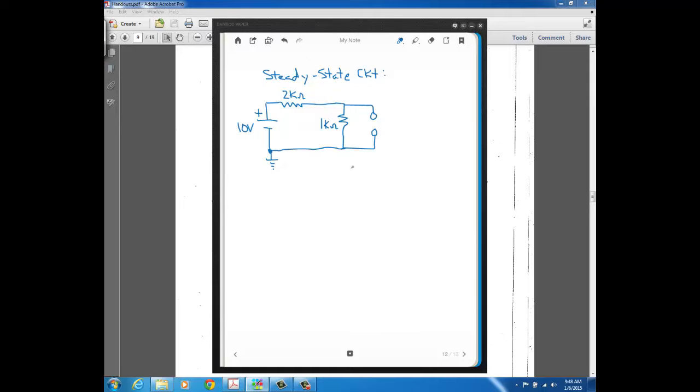the current for the open. Okay, because the current for the open, that's the same as the current for the capacitor at steady state. And I'll put in t equal to infinity here. That's the theoretical value, but as we talked about, in practice, the steady state is 5 time constants. So you could also put 5 taus here if you wanted to. And then the voltage across the open, that's the voltage across the capacitor at steady state.